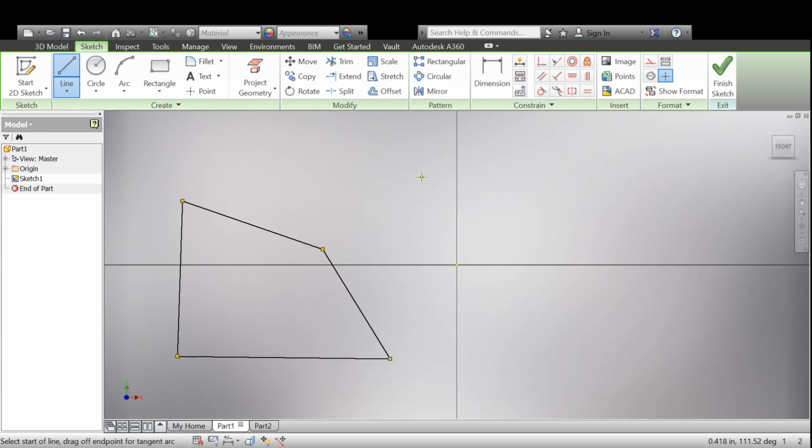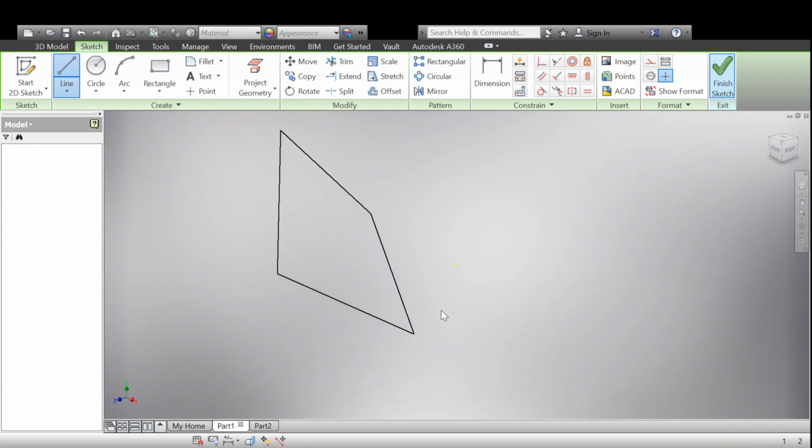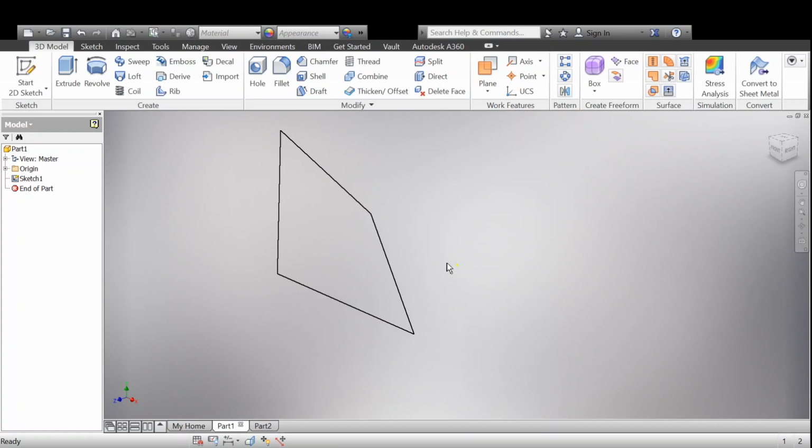Now, with this polygon, I can do a couple of things, and this is what's going to be important for today, for CAD 2 and the upcoming CAD assignments for 3D work. I'm going to now press the following. So if you're looking at your computer right now, pause please, look up. You're going to press Finish Sketch, and you're going to remember several things. First, when you hit Finish Sketch, your 2D image is still there. It's on the screen. I can move the screen to see a little bit better in a minute. But the sketch that you just created is on the left over here. If you do anything with this now and make it somehow a three-dimensional solid, this sketch will still exist. It's not going to go away.